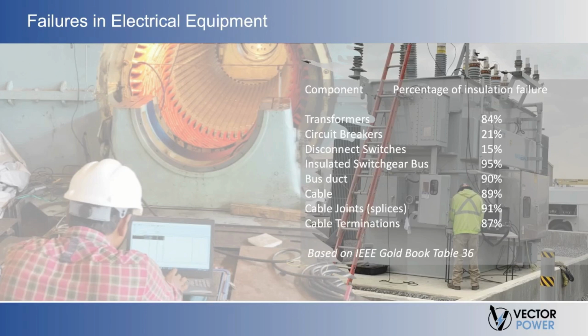So far we stated, most failures of electrical equipment are the result of a breakdown in the insulation system, and dissipation factor or power factor testing is an effective way to detect defective electrical equipment insulation. Dissipation factor is the ratio of the capacitive or the charging current, measured in voltamperes, to the resistive or the leakage current, measured in watts. It is a means of measuring insulation integrity, since the smaller the dissipation factor, the better, or the more efficient the insulator.